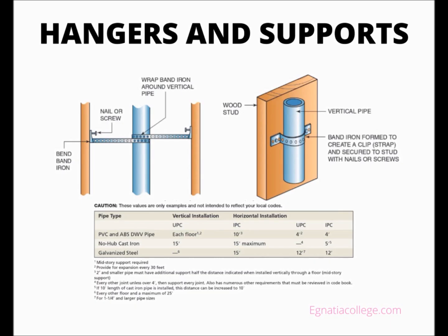When piping is hung in an attic, additional wood must often be added to the ceiling joist. Small pieces of wood in varying thicknesses can be added to the top of the joists to allow the pipe to slope. Another method is to cut longer boards and secure them to the sides of the ceiling joists to control the slope, and then use band iron to secure the pipe to the wood. A more labor-intensive method of supporting horizontal pipe from a ceiling or floor joist is to drill the appropriate size hole through a board and then secure the board to the joists.